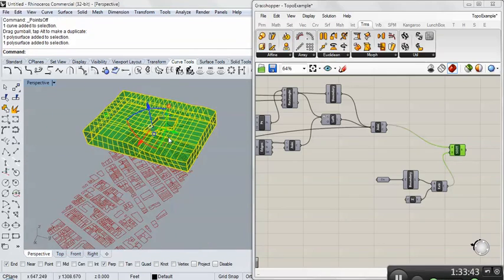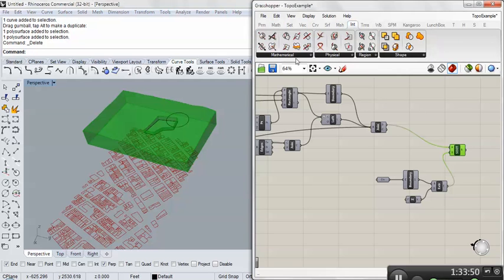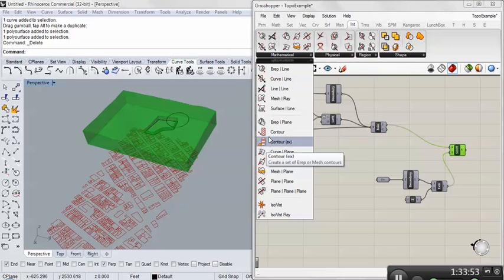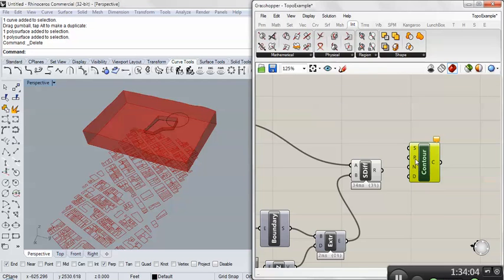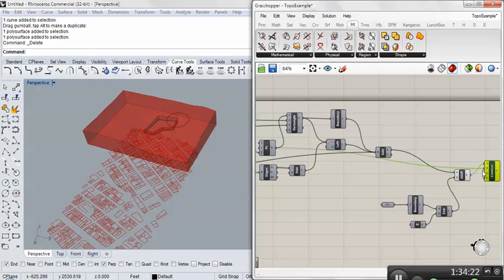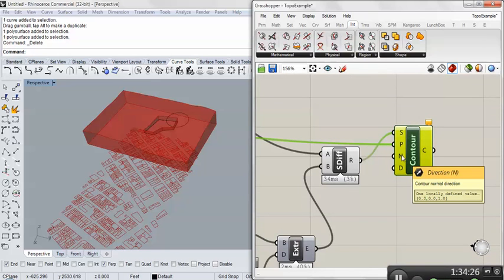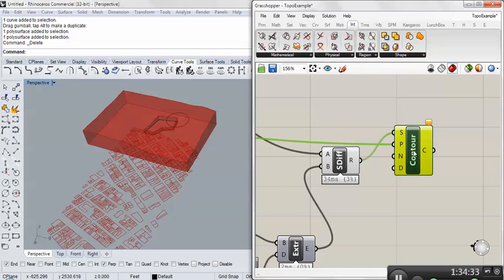That's real geometry. If you cared about the curves, there's a Contour component under the Intersect tab, Math. Contour creates a set of B-rep or mesh contours. So this one needs the surface you want to put contours on, and the base point of your first contour, which we already have. We made that point for a rectangle, so I'll drag that forward. And then you have to tell it the distance, the elevation between your contours. So say we care about 5 feet here. There you go.